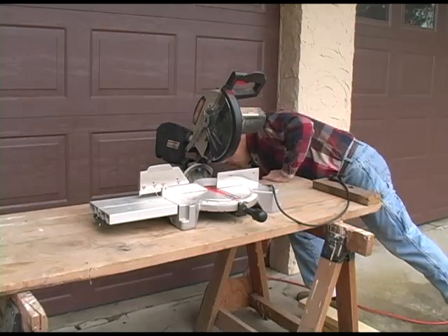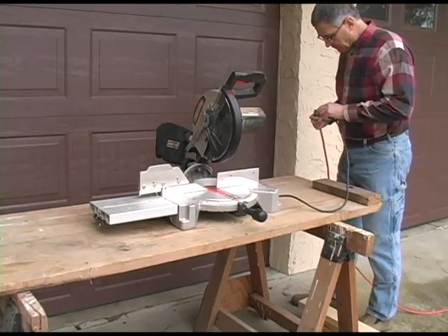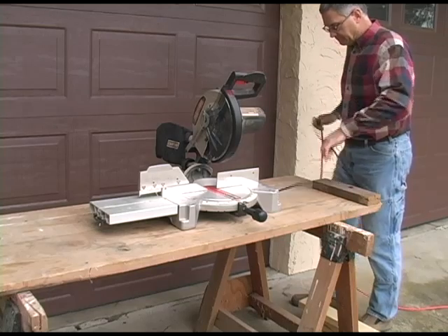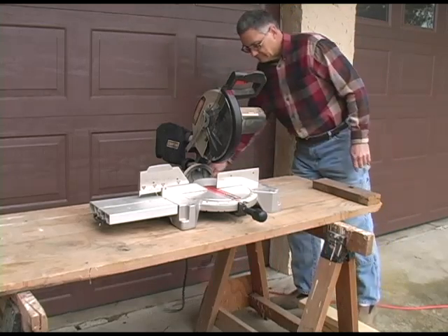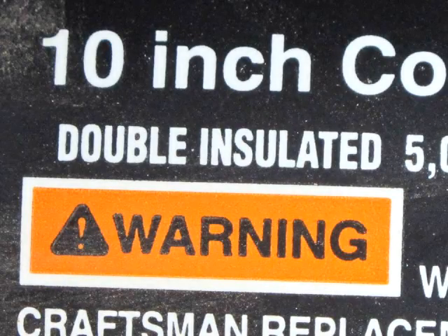Since the saw uses electricity, other engineering controls are employed to protect workers from the hazard of electrocution. For instance, the saw is double insulated, meaning its exposed metal parts are separated from electricity either by an extra layer of insulation or by insulation that is specially reinforced. Electricity is still present, but double insulation reduces the risk.